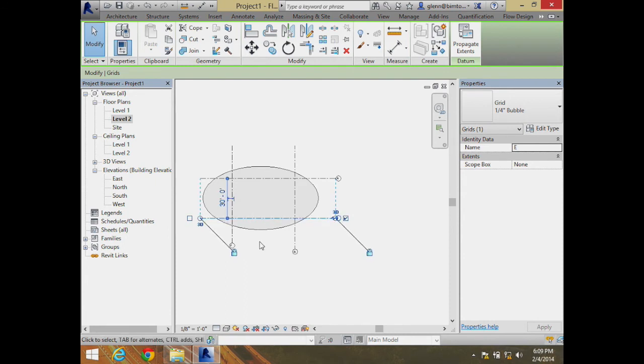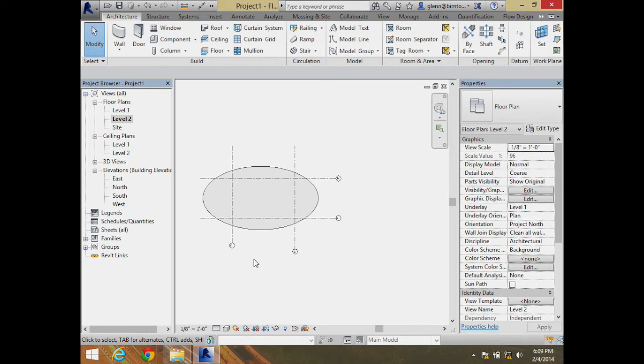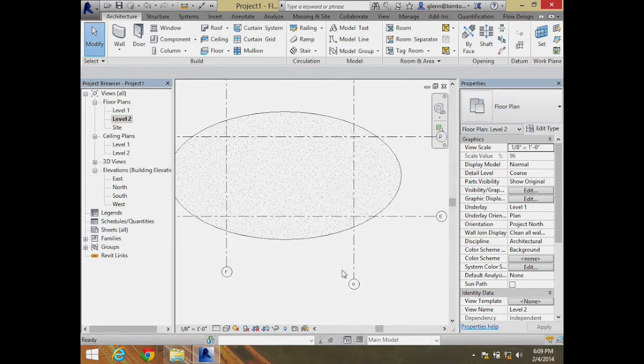Question for you. As we put columns on there, do they have to be right at the outer edge of the building? No. I see some head shaking here. You're absolutely right, they don't have to be. Even the floor itself has a little bit of natural span. You can count on it to hang out a couple feet before you have to worry about the structural support being there. Very often we don't put the columns right at the building edge. With the columns on the inside, the floor can span a little bit, and then the curtain wall just hangs on the floor. It's clipped to the floor and makes a nice continuous sheath going down the outside of the building.